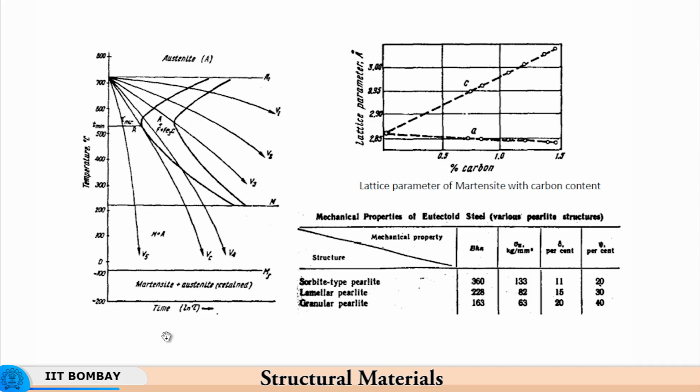Because the martensite start goes slightly above the room temperature and martensite begins to form. As the martensite continuously forms with increasing mechanical working, the entire chunk of material gets transformed to martensite. So the mechanical energy that is imparted does the job.